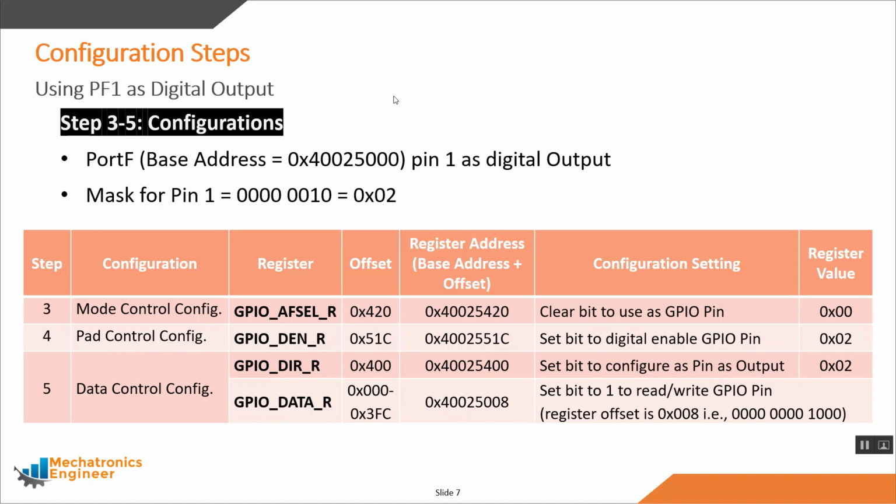Now let's discuss these configurations for port F, because the user LED is interfaced to port F pin 1. This is the base address for port F, and the mask for pin 1 will be hex 02.